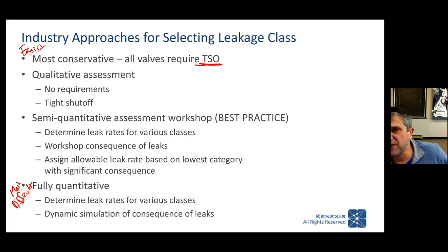of construction. It's difficult for the person who has to test the valve and make sure all those leakage requirements have been achieved. And it's also expensive in terms of the ongoing maintenance, because once you stroke that valve once, it's no longer tight shutoff, so I need to send it back to the manufacturer and get it refurbished so that it is now once again tight shutoff. So I'm not a big fan of the most conservative approach because it's wildly expensive.